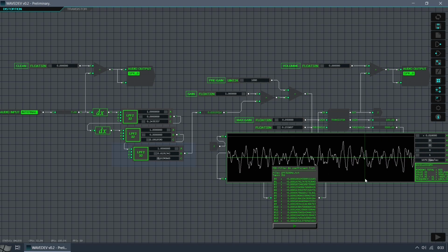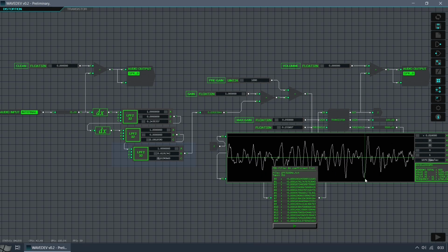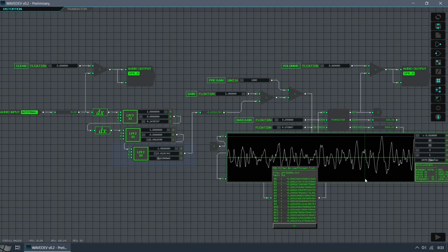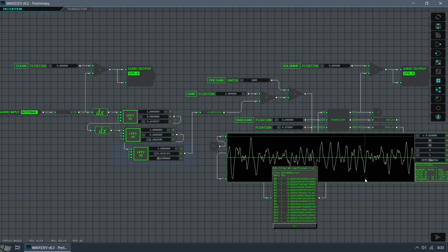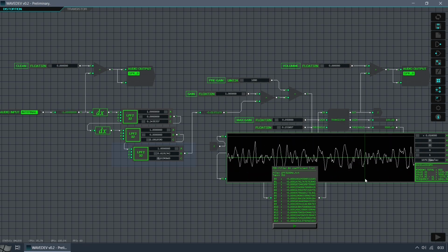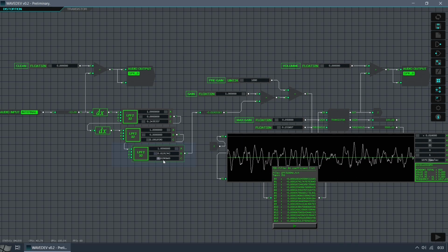The issue here is that noise is more than just high frequency. It is present in the entire spectrum. This means that we also have noise below 3.1 kHz. Since noise moves randomly along the spectrum, its frequency may coincide with the resonances of the system. So the noise can also be boosted by resonant filters.